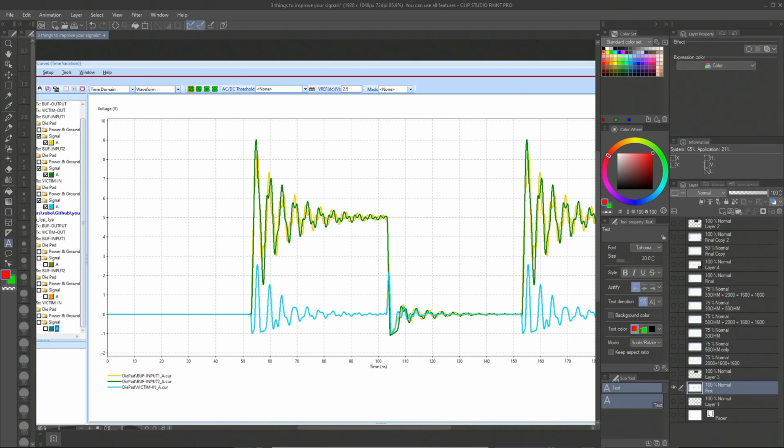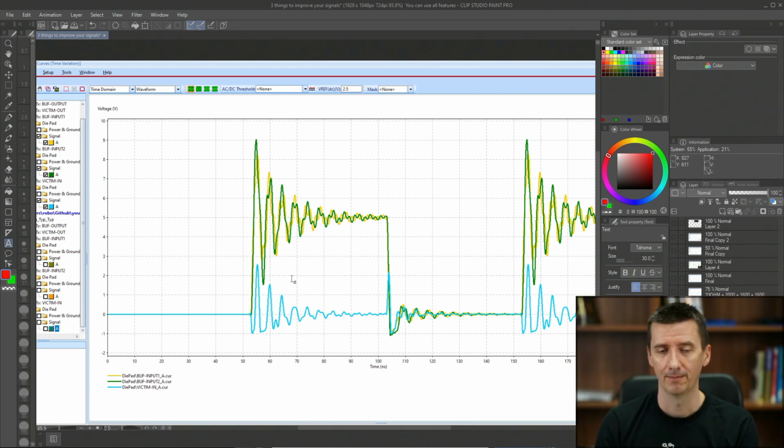Why your scope may not show this correctly? Do you know? One of the biggest reasons is that to show this kind of signal, your scope would need to have a very high sampling rate, and this is usually possible only in very expensive scopes.